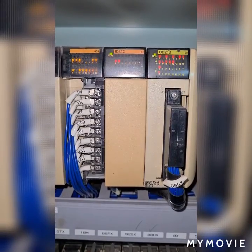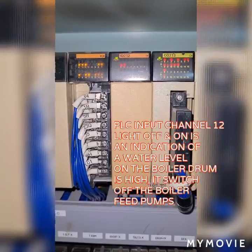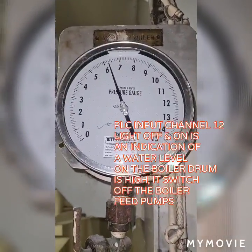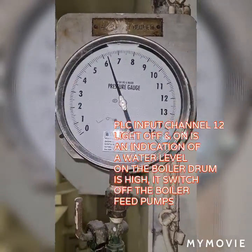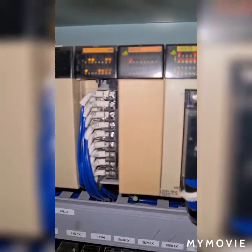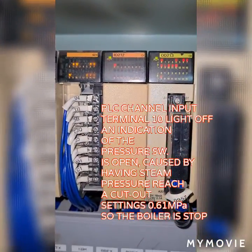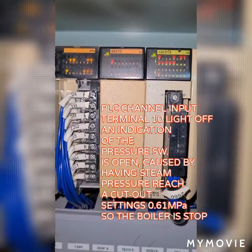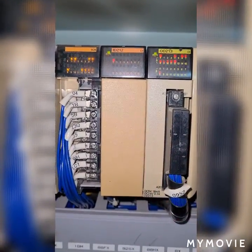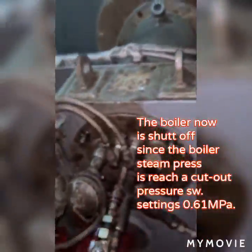As you observe, the input channel 12 light is switching on and off, meaning the water level of the drum is being monitored. If the steam pressure of the boiler reaches about 0.62 megapascal, the PLC input channel number 10 light will be off. The boiler now is off.